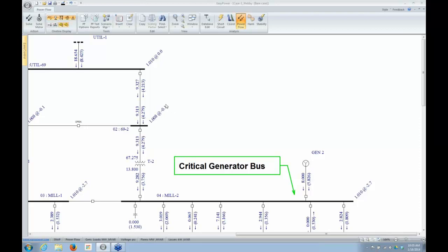So if you have a complex situation where you have multiple generators and utility sources, you may have to create some different scenarios to model different cases and switch back and forth between PV and PQG and swing. Normally the utility source, the most substantial source, should be the swing source for your power flow.